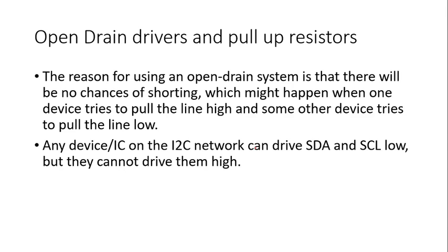But when you are having the open drain drivers, you can directly short circuit many devices. It means the pins of many devices you can directly connect to each other without actually shorting the VCC and ground. Okay, and for that it is using open drain drivers.